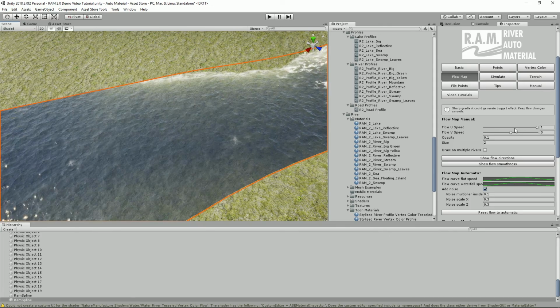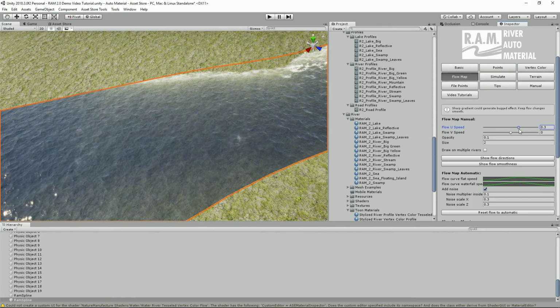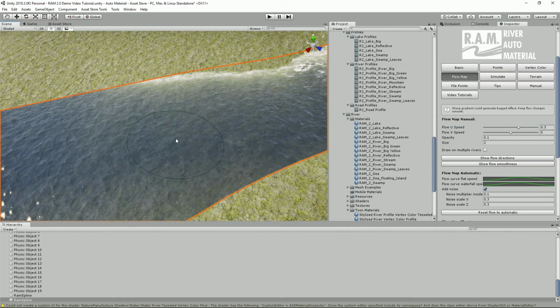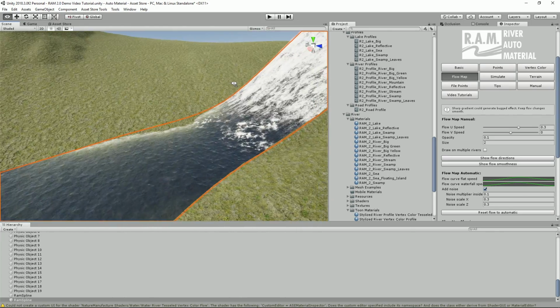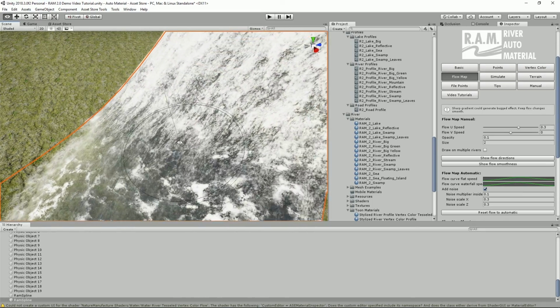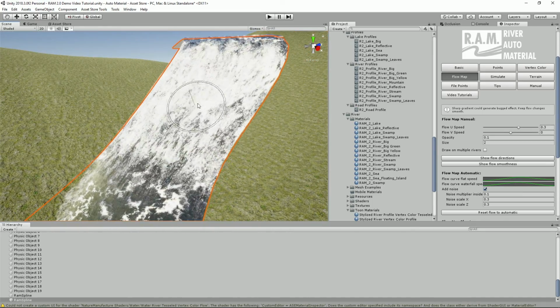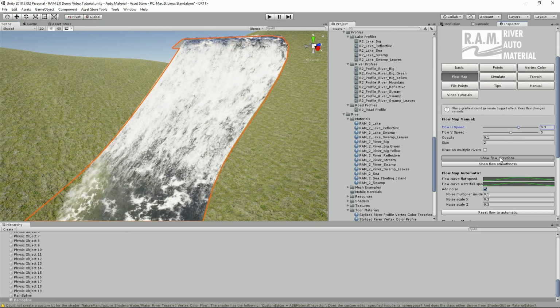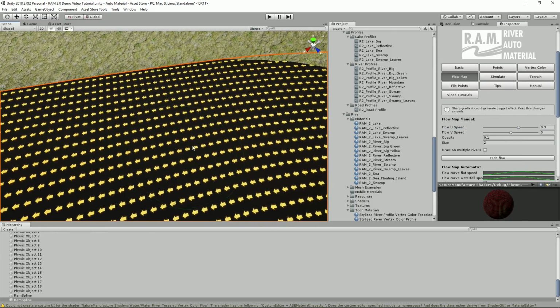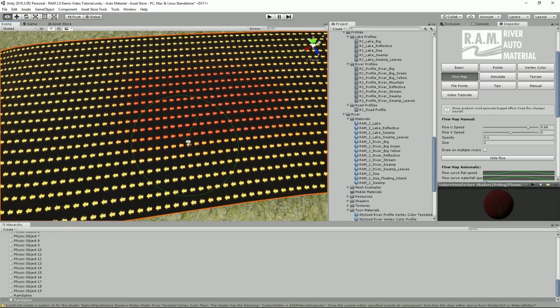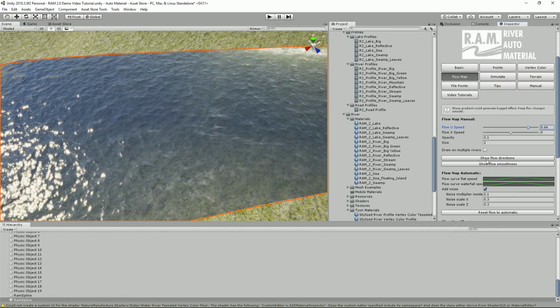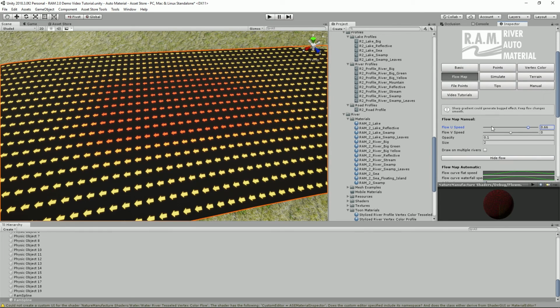Now we will play with manual painting. We will increase speed of the water in the middle of the river by brush. Remember to keep this smooth because simply with hard blend it will generate artifacts on UV. We have debug and the arrows show direction of the water, colors show the speed. For example, we could even invert the water flow.